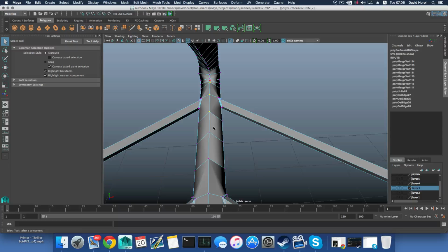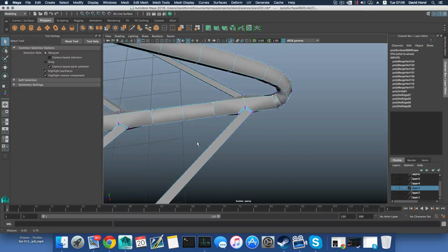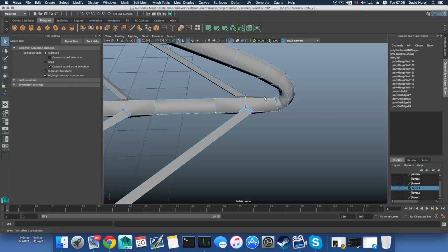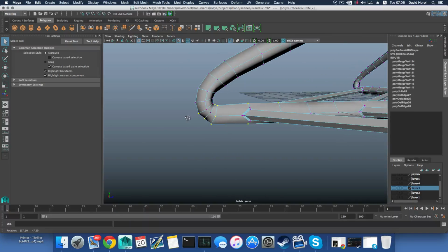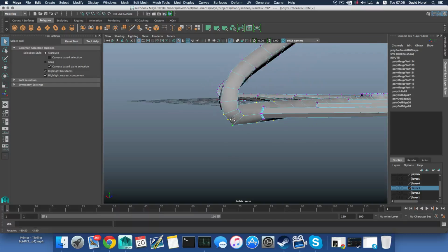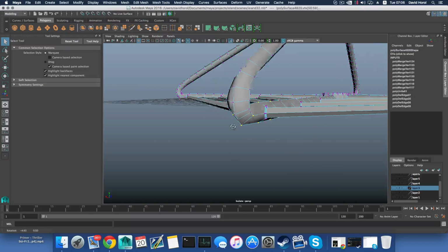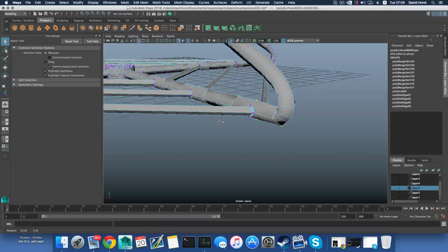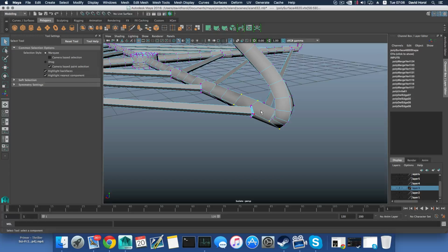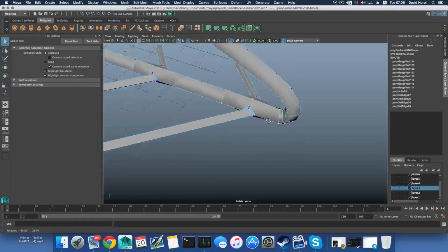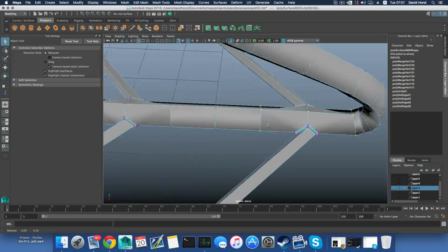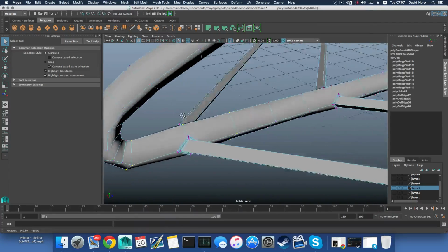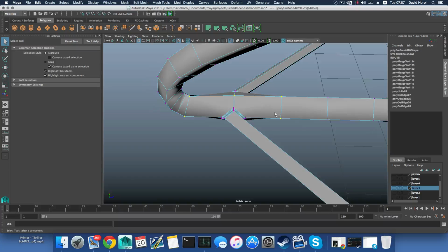So I'm gonna connect the centers and Control Shift select these and Control Shift select these. These ones are needed. This is not where I cut it. Now these also are already attached to those 4 faces, so I don't need to select them. If I would select them, this is really dense and they would merge. I don't need this to merge. I need only those to merge.